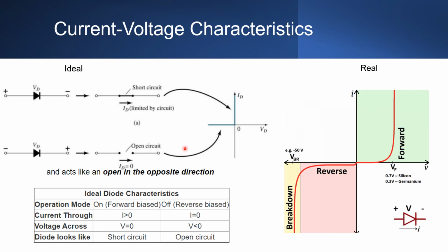As long as the voltage across the diode isn't negative, in this part, it will turn on and conduct current. Ideally, a diode would act like a short circuit, meaning there is 0 volts across it while it is conducting current. When a diode is conducting current, it's forward biased, the electronics jargon for on. This table shows the summary of the characteristics of an ideal diode.